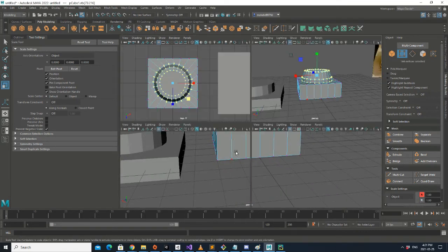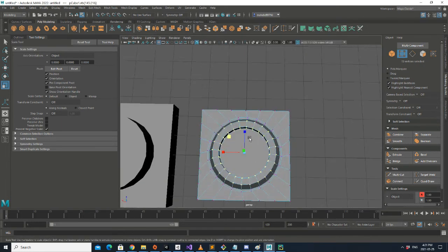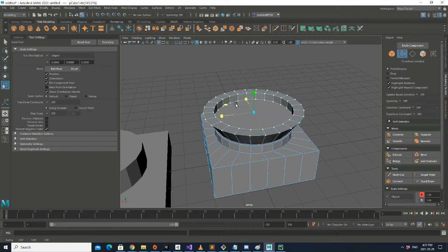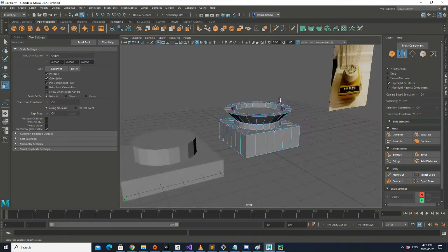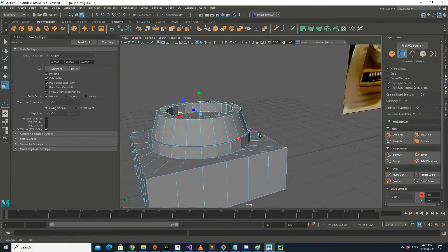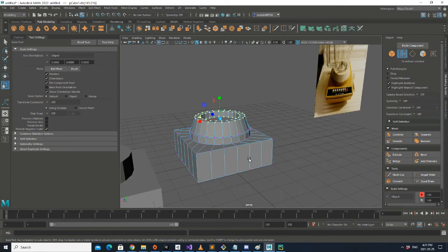And again, for example, if I wanted to only make these last vertices smaller or bigger, I could just select these ones I wanted. It's completely up to you on what vertex you choose and what you want to do. But the scale is very helpful for moving all the vertices, especially in symmetric objects, uniformly along some directions to make them smaller or bigger.